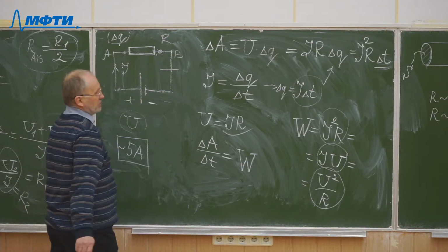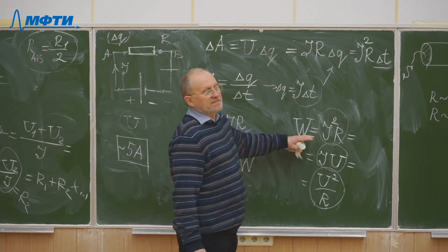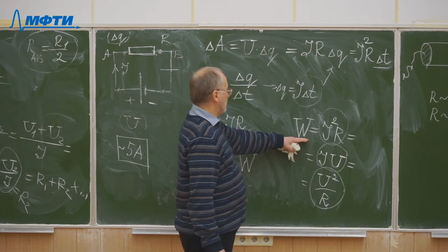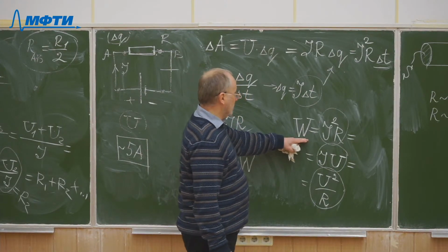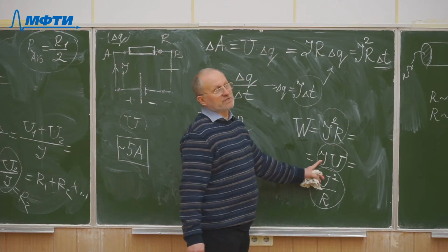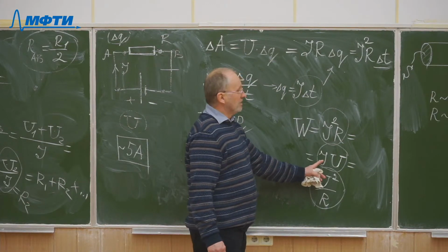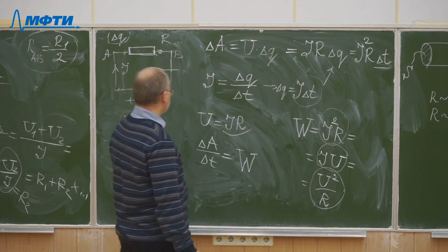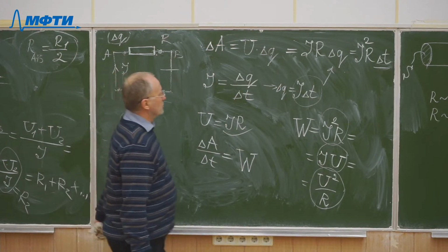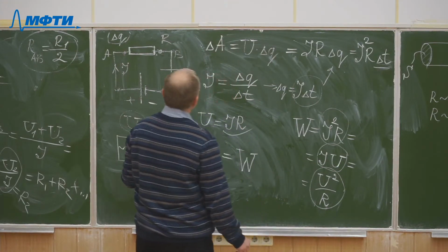So if you want to have some electrical appliances attached in your house of certain electrical power, then you may easily calculate the current which must be sustained in your wiring, in your circuitry, and then you may calculate what fuse you should use in your electric circuits.